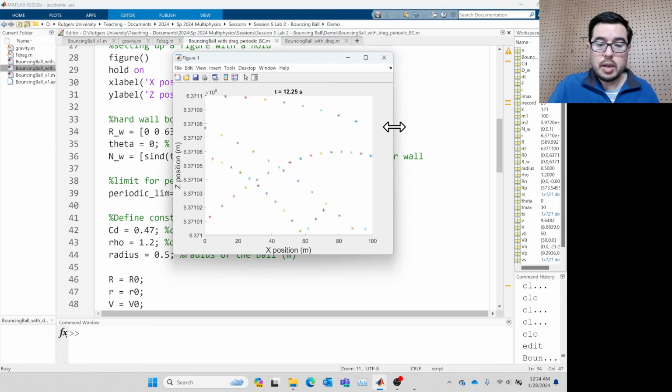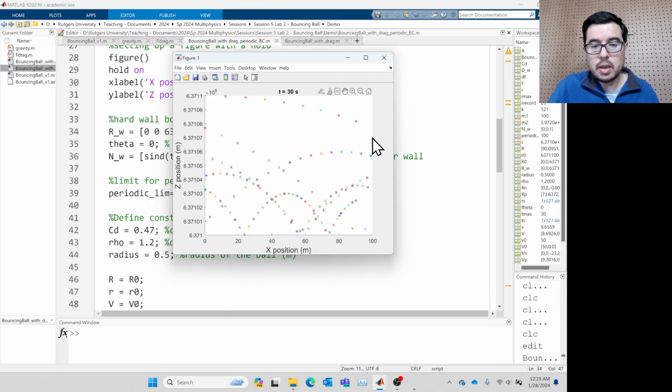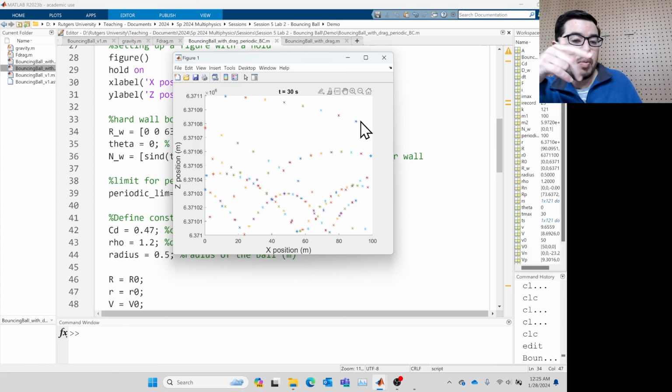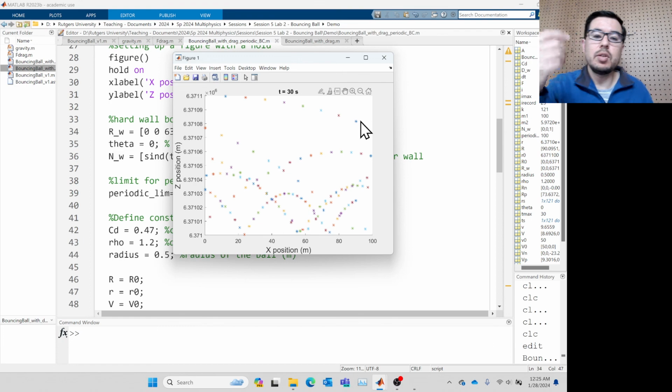Look at that. So it got to 100, and you see the time step. Maybe a smaller time step, because it's over here, it's kind of a significant amount, but then it came back over here to 0. But that's the thing, depending on the size of your time step. Well, actually, remember we're only recording every quarter of a second, but we're running at 100 times per second. So it's actually not the time step's fault, it's the recording frequency's fault, or the sampling at which we're recording.